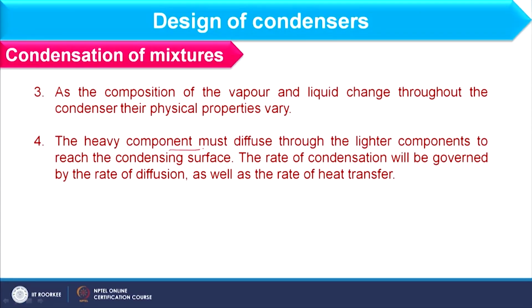So, the heavy component must diffuse through the lighter component to reach the condensing surface, and the rate of condensation will be governed by the rate of diffusion as well as the rate of heat transfer. So, these are a few points when I am dealing with a mixture instead of a pure component.